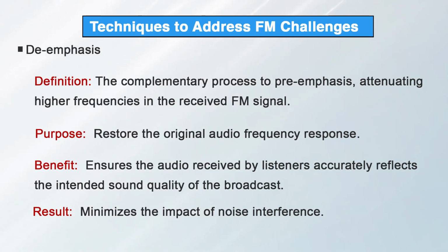So, by applying de-emphasis during reception, engineers can ensure that the audio received by the listener accurately reflects the intended sound quality of the broadcast, minimizing the impact of noise interference. So, in conclusion, while frequency modulation offers superior audio quality and resilience compared to amplitude modulation, it faces challenges related to signal fidelity and noise interference.